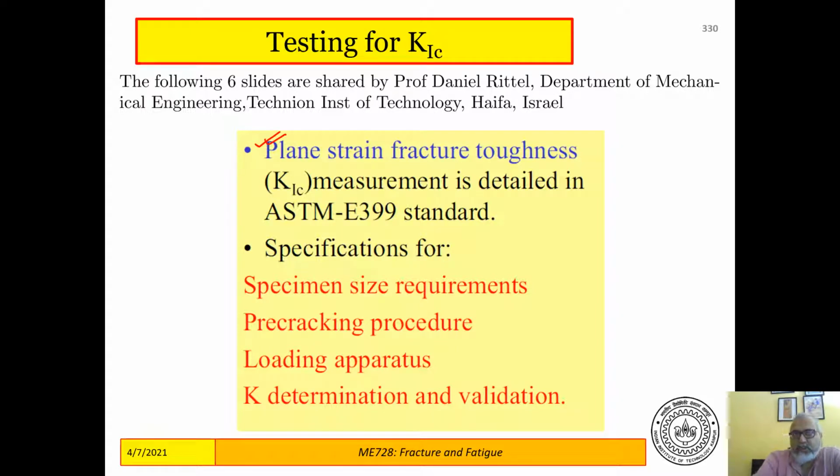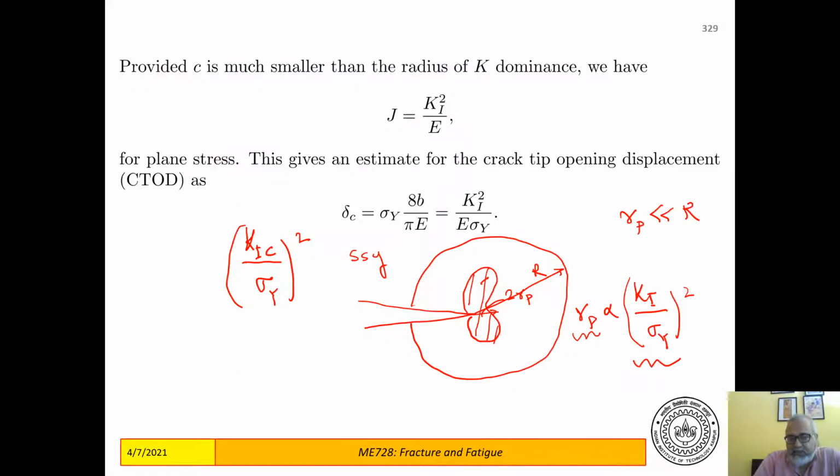plastic zone is smaller than the plane stress plastic zone. Towards the outer free surfaces of the specimen, you have close to a plane stress situation, whereas deep inside the specimen you have a plane strain situation. So our fracture surfaces that you get in thin specimens, which are thin in breadth, is not the same as you get in case of thick specimens.